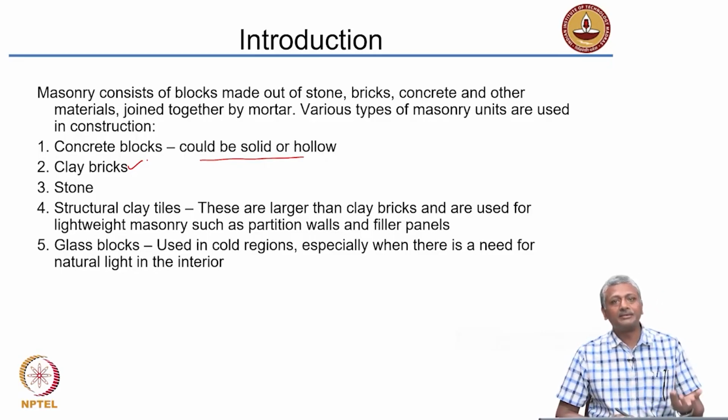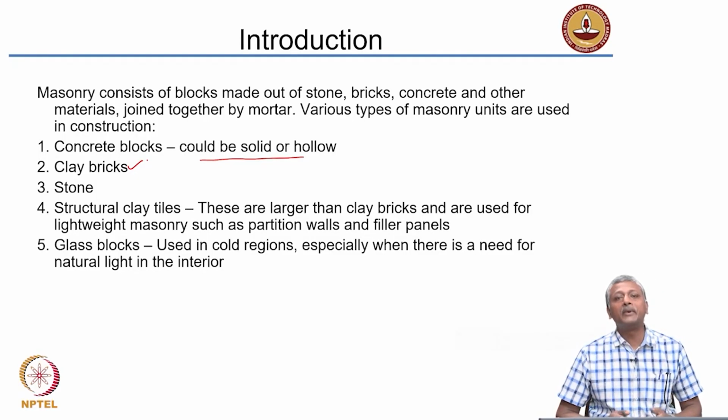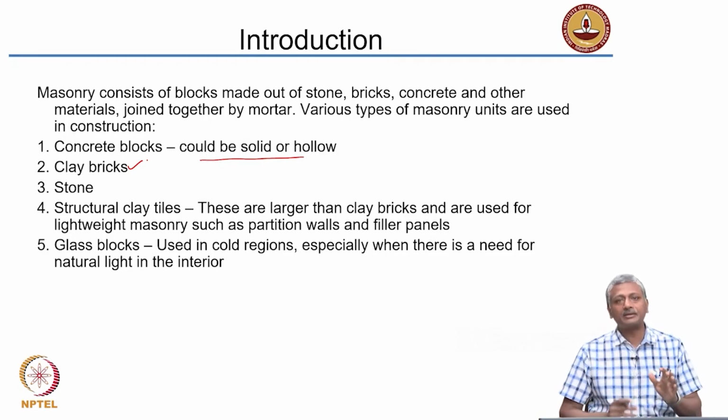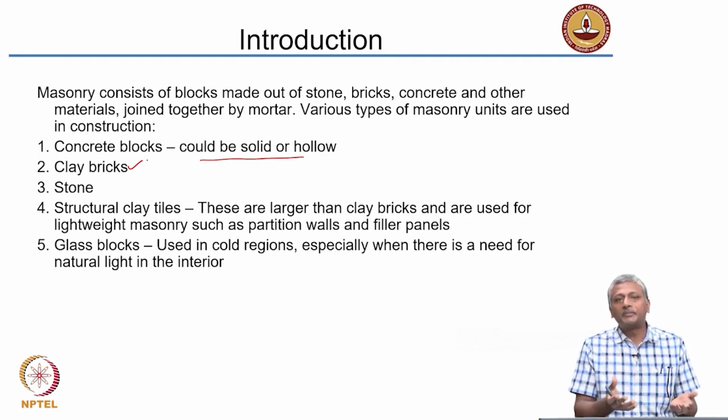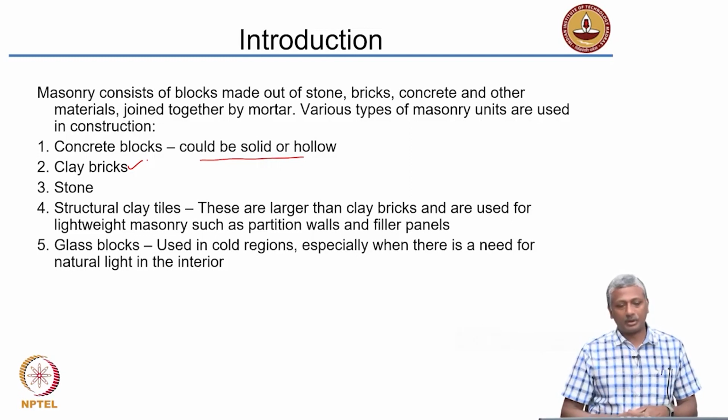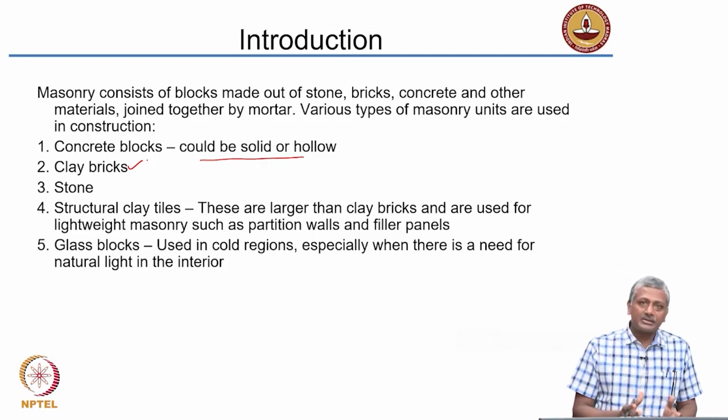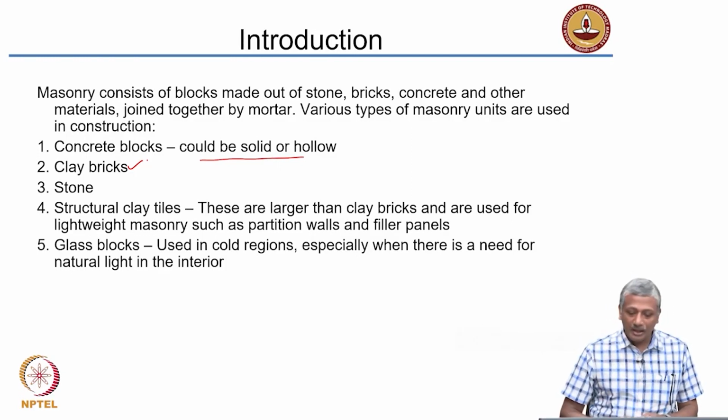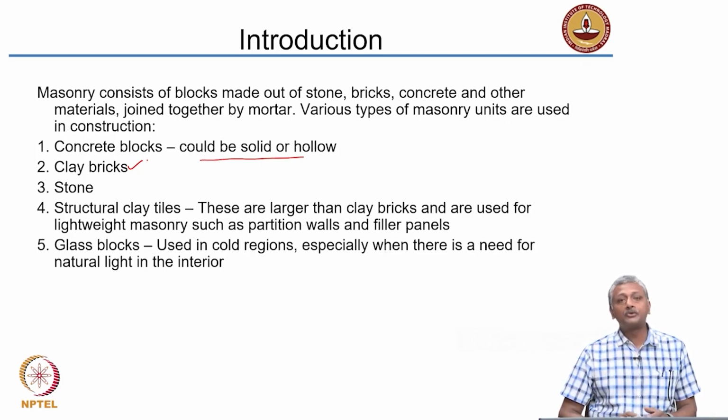You can actually make structural clay tiles to bear load. So in masonry, basically, the components are bearing load. A typical tile which you put on the floor is not bearing as much load as a block that is supporting a wall. Okay. So structural clay tiles are designed to be larger than clay bricks and can be used for lightweight masonry such as partition walls or filler panels. We are not going to talk about that in much detail here.